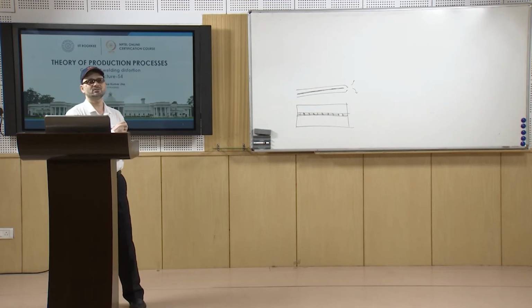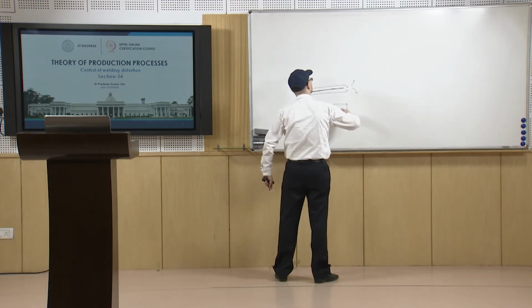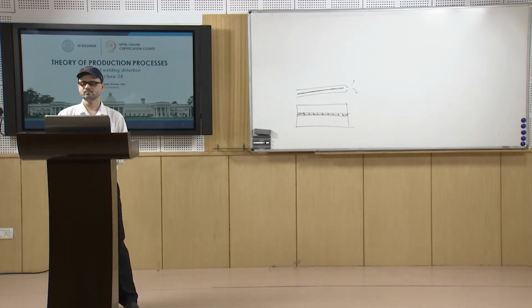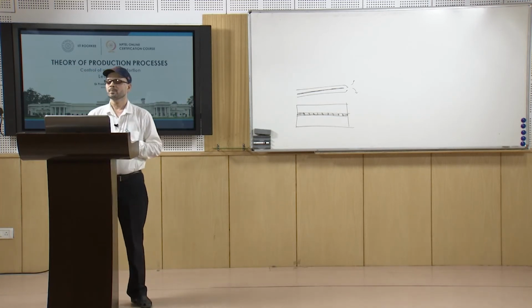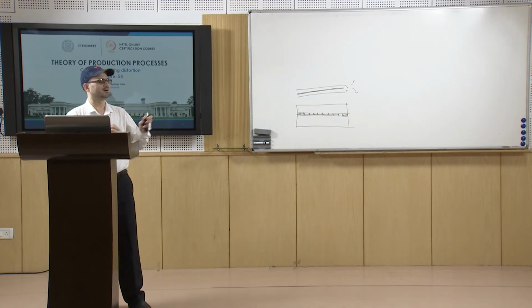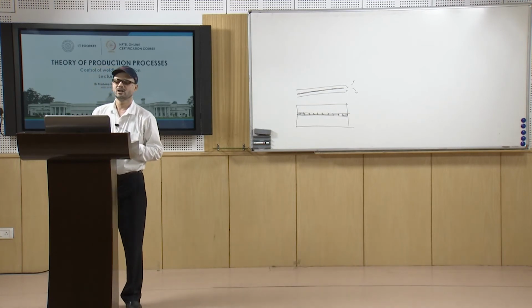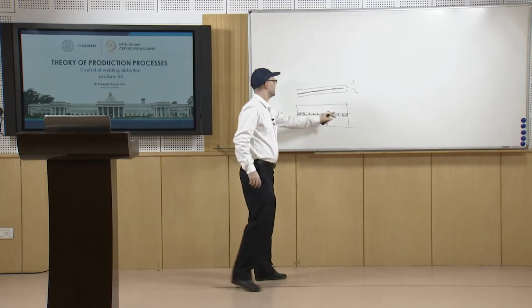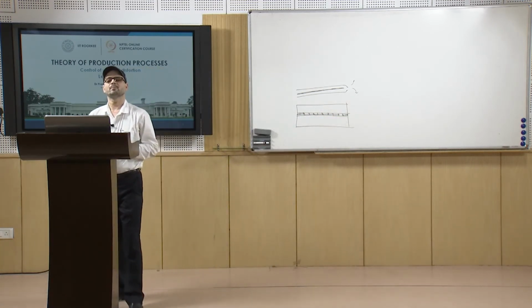So, it is known as a back step welding sequence. The welding direction is the same, but we are moving in this fashion. So what we do is we tack weld from one end to the opposite end. First we do the ends, and then the remaining layers also, alternating the directions. So we do from here to here, then from here to here. This way the tack welds are applied.